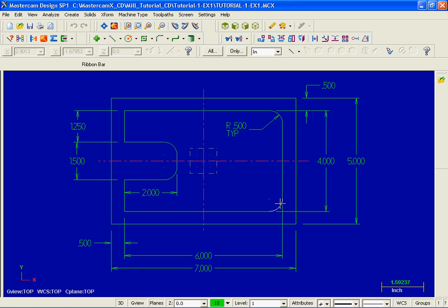I'll use Create Rectangular Shapes for this, and yet another rectangle which measures 2 inches by 1.5 inches, and it also has 0.5 fillet radii on the right hand side. After we have the initial geometry created, I'll use Trim and Delete to clean things up. Let's get going and start a new part and start creating the geometry for this exercise.